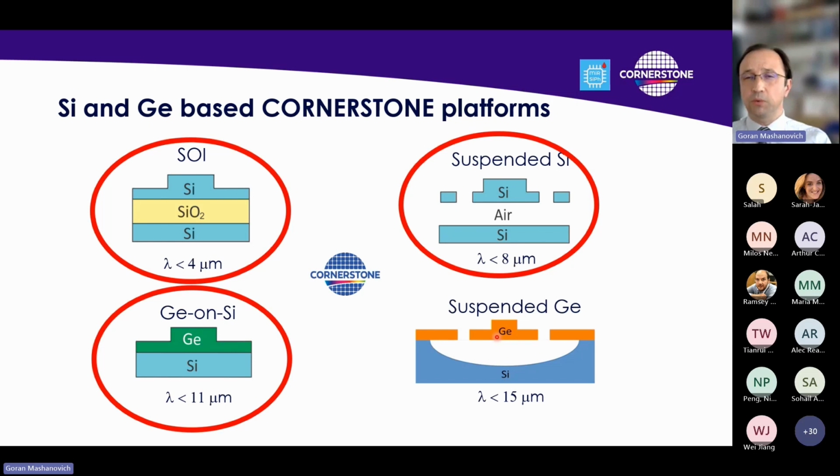And also we want these waveguides to be low loss, such that we can have large spirals, we can have tens of centimeters or maybe even the order of meter waveguide such that there is a large interaction length between the optical mode and an analyte. So figure of merit could be this evanescent field over the loss.